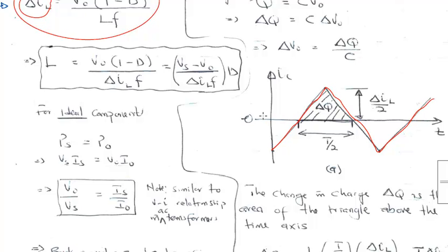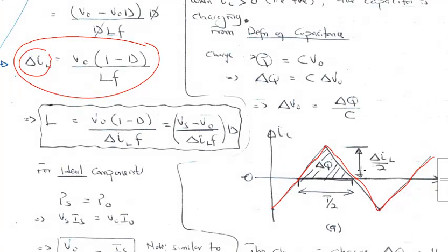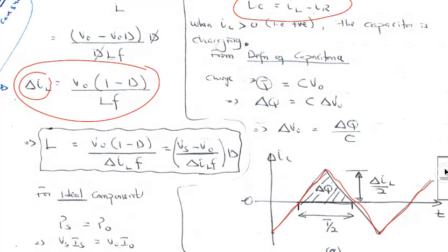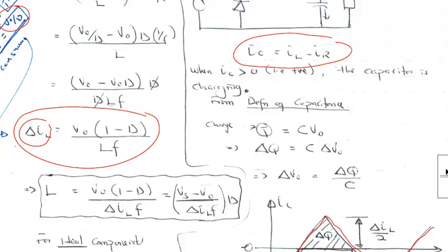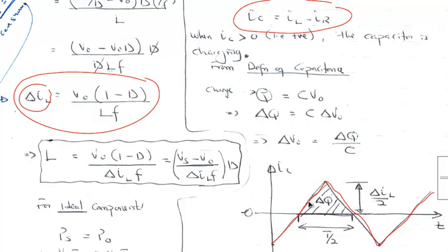So we are going to see that in one cycle we have the capacitor charging up, okay, when the current is positive. So far as the current is positive, we have the capacitor charging up. When the current is negative, we have the capacitor discharging. This is what is going to create the ripple across the output voltage. This is what is going to create the ripple.